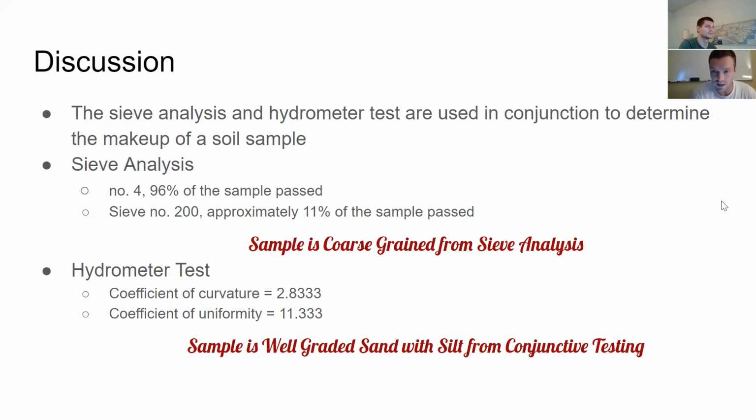Upon further classification using the USCS table, 11% of the soil was made up of fines. This qualifies it as a sand with fines. From here, we must use the hydrometer test to answer further questions regarding sand classification. The hydrometer test will explain how to proceed now that we have reached a threshold that lies between the given parameters of 5 and 12% fines stipulated in the USCS.